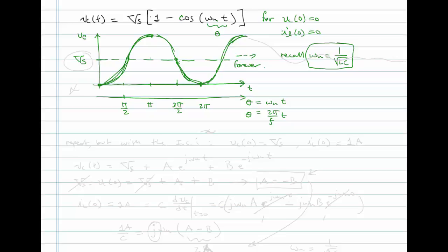If it were to die down, it would die down ultimately at Vs, which we found to be our particular solution. It just so happens that in this case, because there is absolutely no resistance, we just have an ideal inductor and capacitor. That's like having an ideal mass in a spring. There's no friction, there's no drag, nothing. It would just oscillate forever.